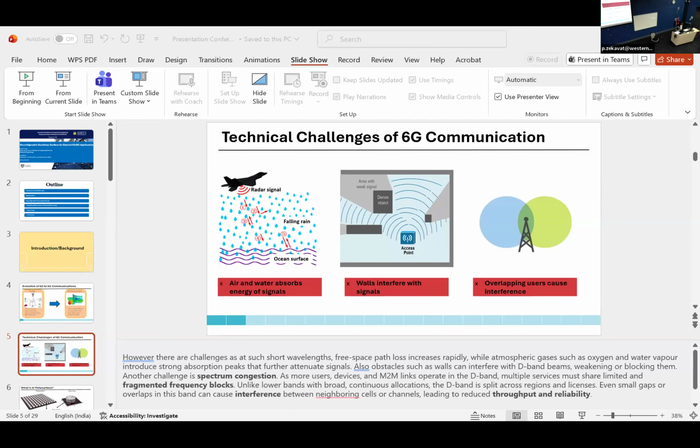So therefore, by adjusting the on and off conditions of the pin diodes in the metasurface structure, this achieved a dynamic shift in both the transverse electric and transverse magnetic normal modes, confirming it works under different electromagnetic field orientations.